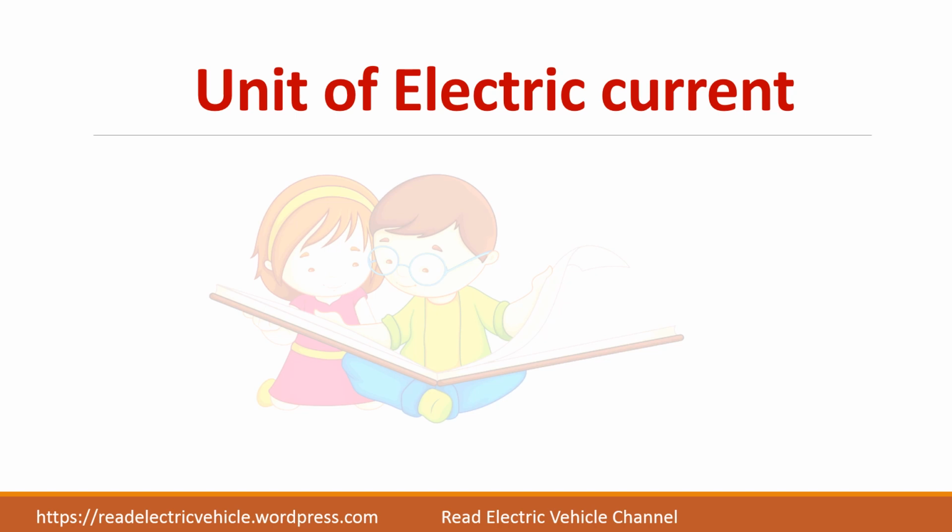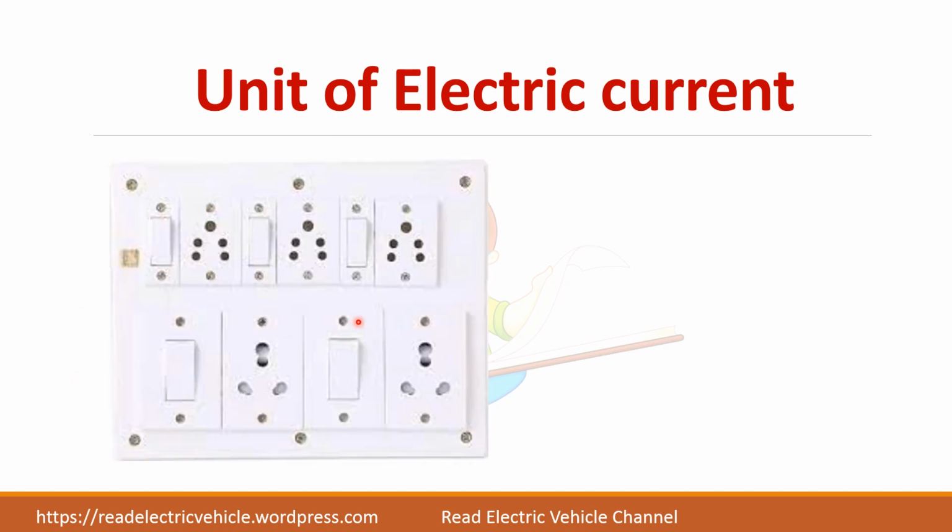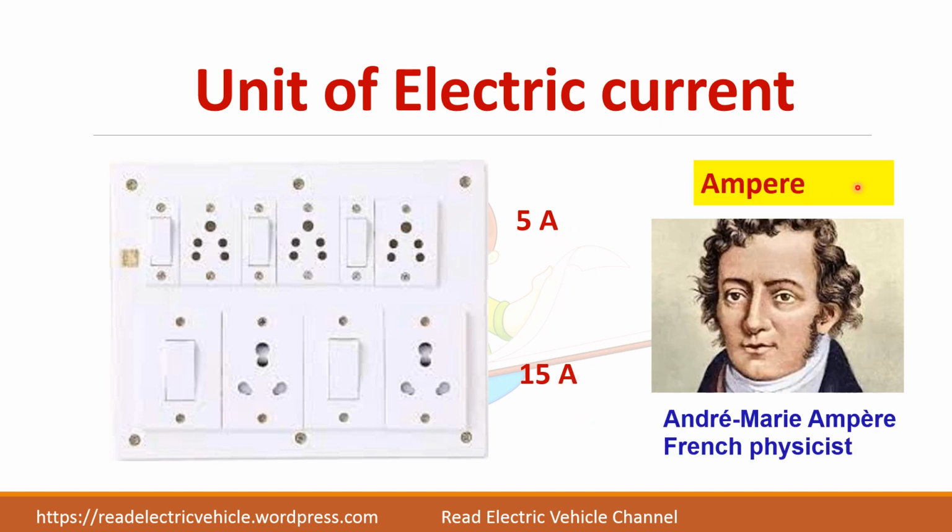Now let us see about the unit of electric current. You take the switches. What type of switch is it? It's a 5 amp switch. It is used for small appliances. Normally we connect a fan, tube light, everything to this type of switch. And if you want to connect a heater or kettle, you will use a 15 amp switch. So what is the unit of electric current? The ampere is the unit of electric current. It is named after the scientist who invented Ampere's law.